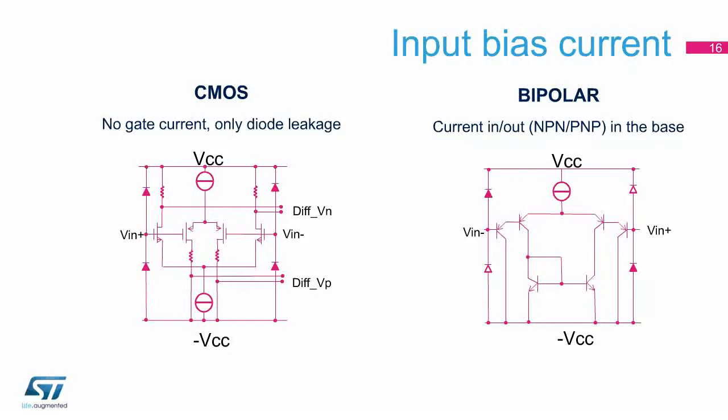The technology used for the op-amp can significantly impact the whole precision of a system. The input bias current parameter, IIB, is defined as the average of the current into the two input terminals with the output at a specified level. The input circuitry of all op-amps requires a certain amount of bias current to operate properly. The input bias is defined by the following formula.